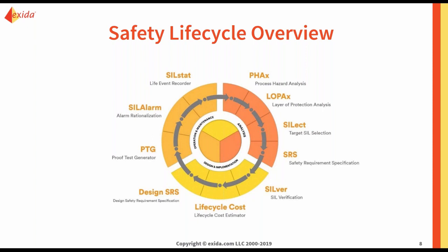The design team will receive that and do the conceptual design and SIL verification. So here you're choosing your devices, you're modeling your SIF architecture, and you're putting together your proof test strategy. What are your proof test intervals? What's the proof test coverage based on the proof test procedure?